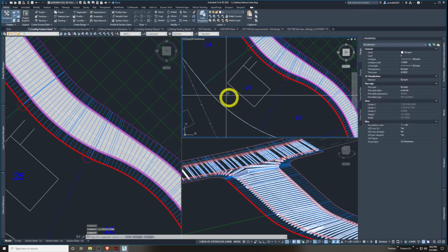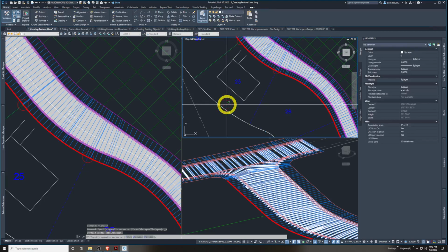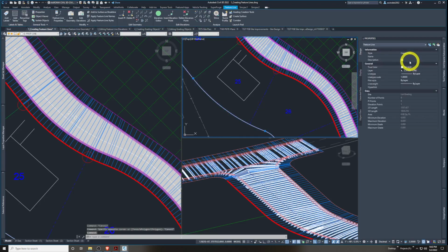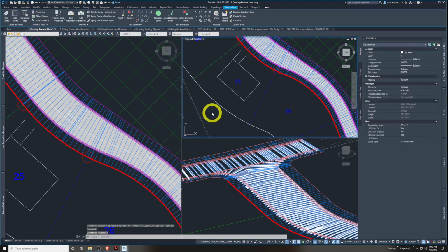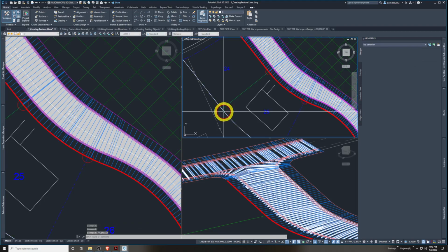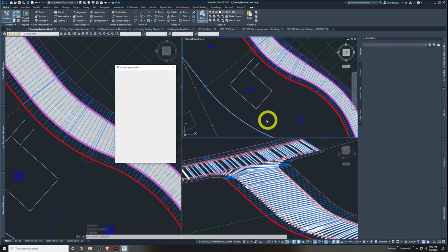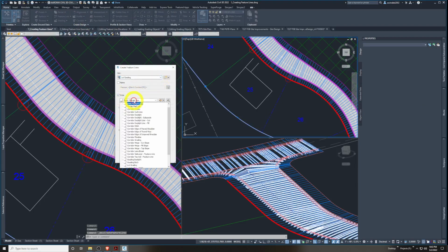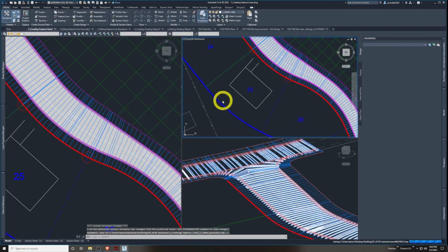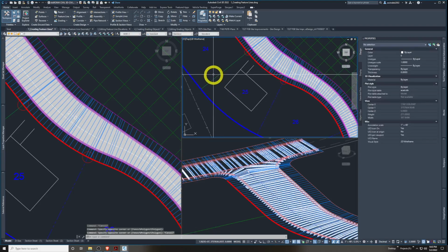Or we can hit Control Z to undo this. A couple more times. So I got it selected. Now I'm going to create feature lines from object. I will do basic. Let's do lot grading feature line. I'll say erase existing entities. There we go. It's a little different color. That's a different style of a feature line. I just don't want to deal with those arc commands.